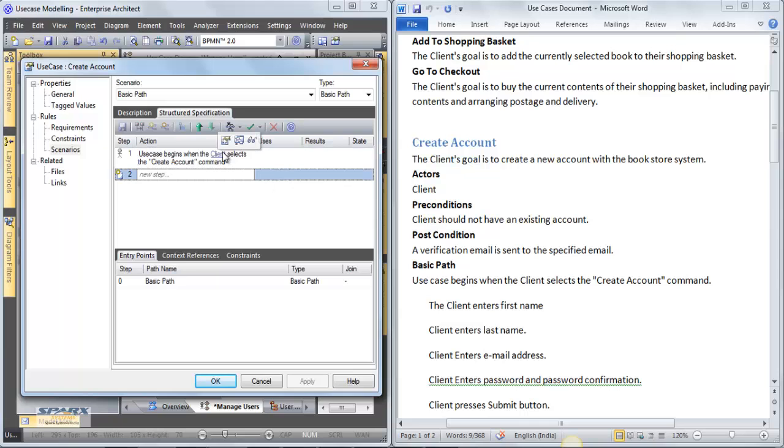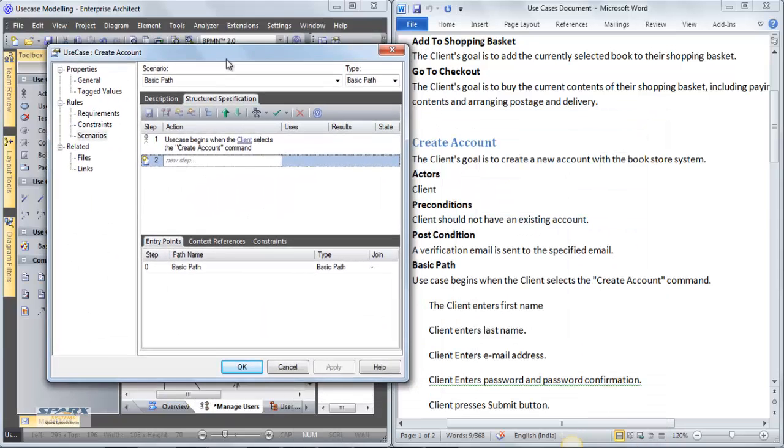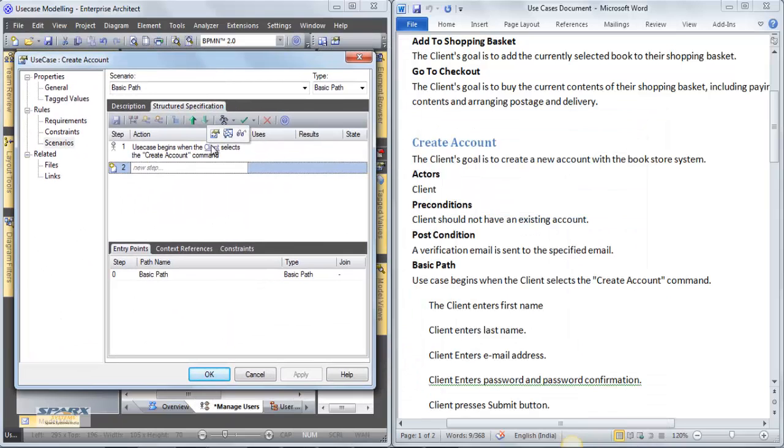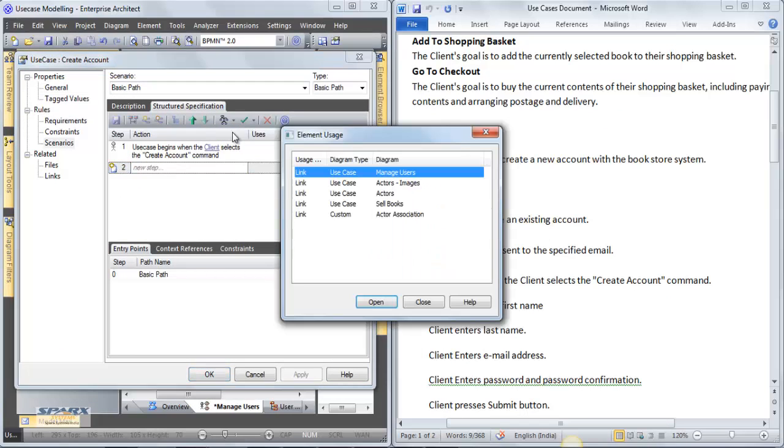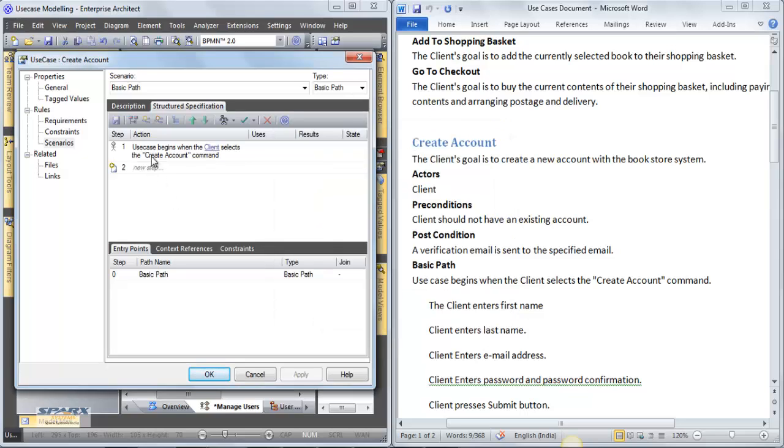Enterprise Architect will automatically add known contextual references to text as you type, like the one for client, where the client is the actual actor in a model and used in various other diagrams. Here we also notice that I typed in use case without a space. These inconsistencies can be avoided by using the IntelliSense information in Enterprise Architect.